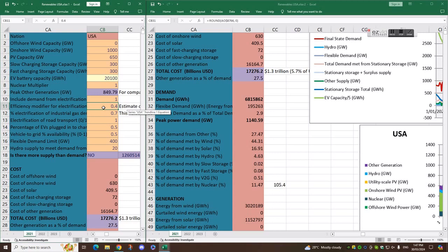So, when electrifying the commercial and residential, the blue and green sections of the graph, I'm saying most of that is being used for space heating. We can see the vast majority of it was in winter when the people are using it for heating. So I'm saying if we substitute electric heat pumps, which are significantly more efficient than the gas furnaces for central heating and so on, we can save a lot of energy. We're going to save 60% of energy because the heat pumps are so much more efficient.